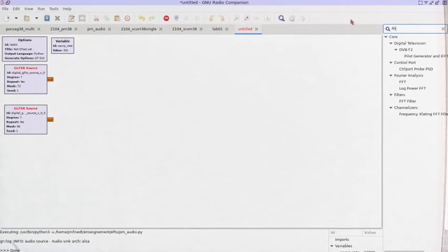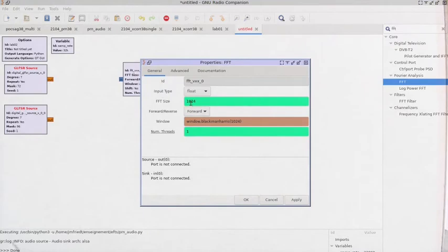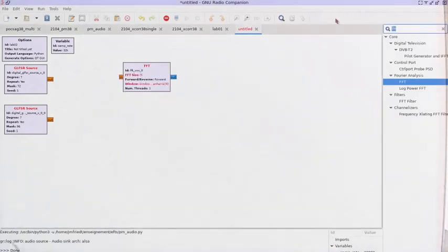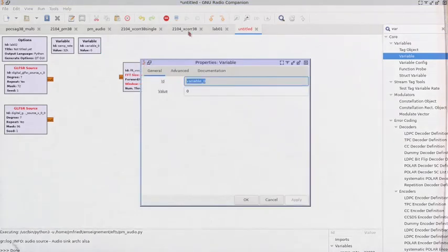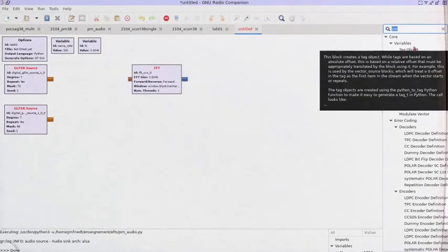We're going to take the Fourier transform, but this time not of the complex but the float. We select a variable n, the number of terms in the Fourier transform, and we create a variable with n, the length of the correlation, which again is equivalent to the pulse repetition interval in a radar system, how often the pulses are emitted.